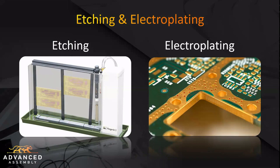So if your board stack-up requires 2 pieces of 2-ounce copper on internal layers, basically the fab house is going to be pulling out a sheet of 2-ounce copper clad material, depending on your core substrate requirements. From there, the core is imaged and then etched away with the copper remaining to create the pattern, or what we call artwork, and spaces of your PCB. From there, you're going to laminate those 2 sheets together in a press that is controlled by time, thermal rise, and cure, along with your outer layers. And then you're going to build up the outer layers and via holes with electroplating.